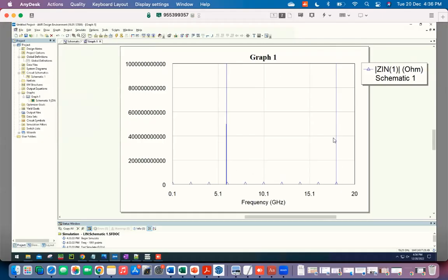So here are the two frequencies. One thing you can already see is that for lambda by 4, the second mode is very far away. So in terms of whether to worry about the second mode, that is already in a very good situation, because for a 6 gigahertz system, you have 12 gigahertz of space between the two. And usually you're going to work with some IQ resonator that might have a line width of 3 megahertz. So you're very, very safe in that respect.